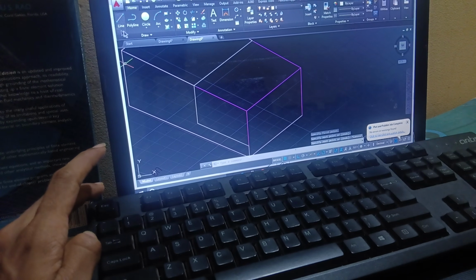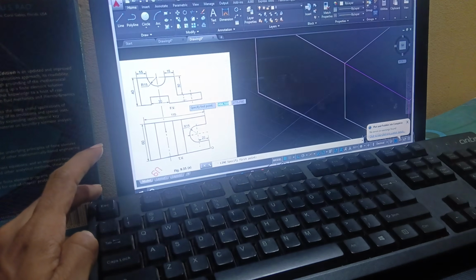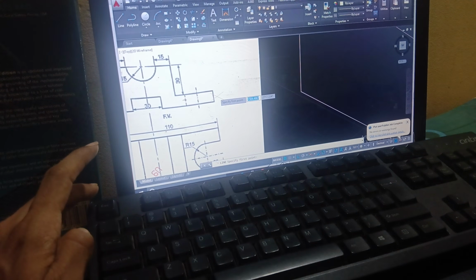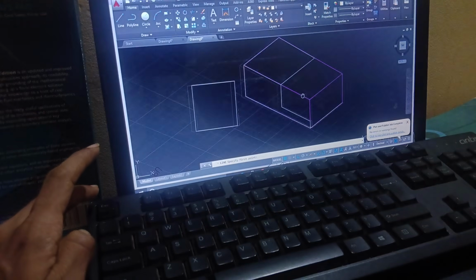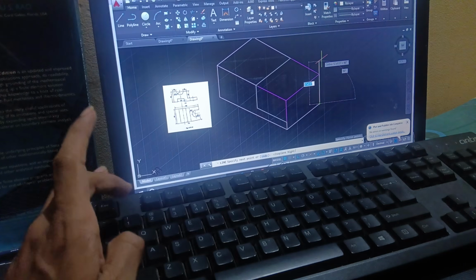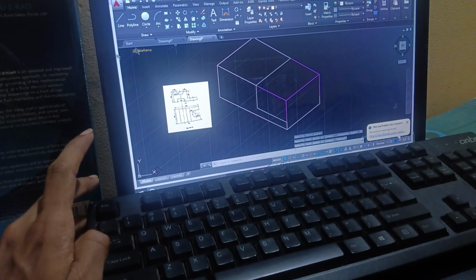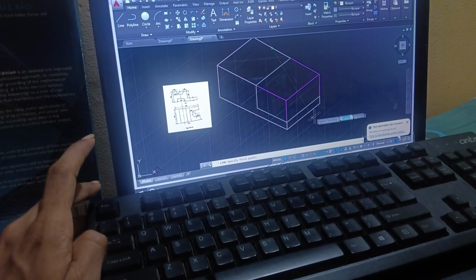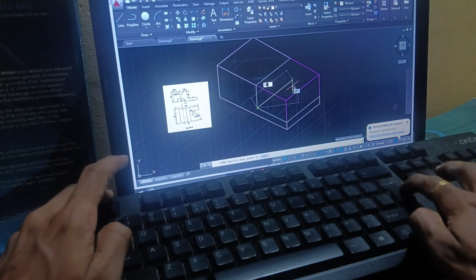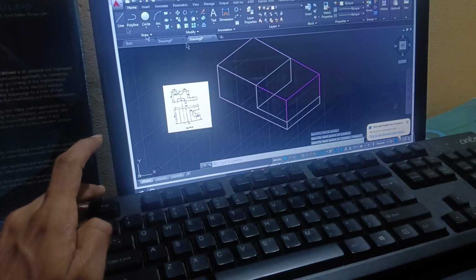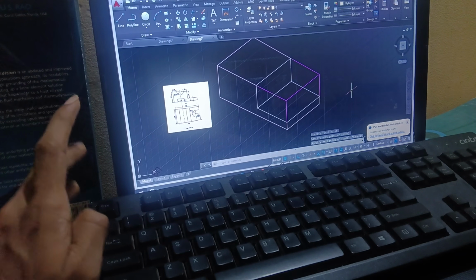Now from this corner draw a vertical line, you can see here. So as this is 30 and this is 40, this height is 10 mm. So from this corner press F5 for the vertical direction and enter 10 mm. Escape. Join these two endpoints. Now from this corner in the x direction, take a distance of 60 mm, join these two endpoints, escape, then join these two endpoints.